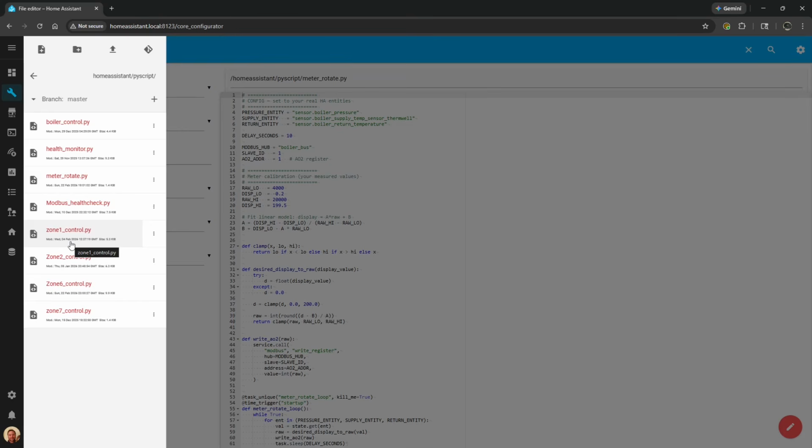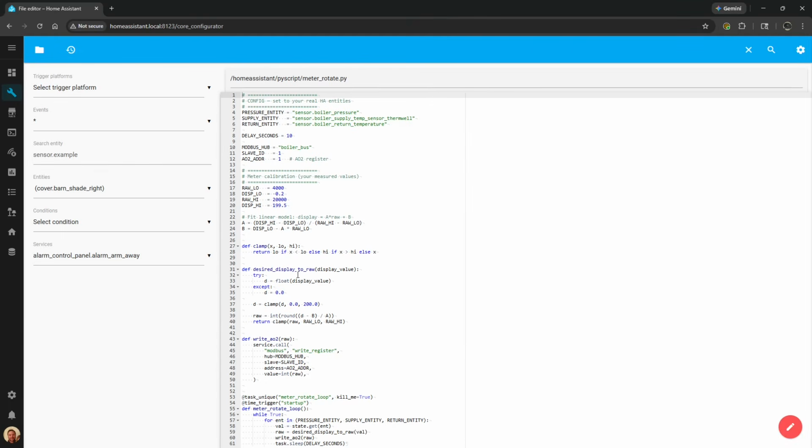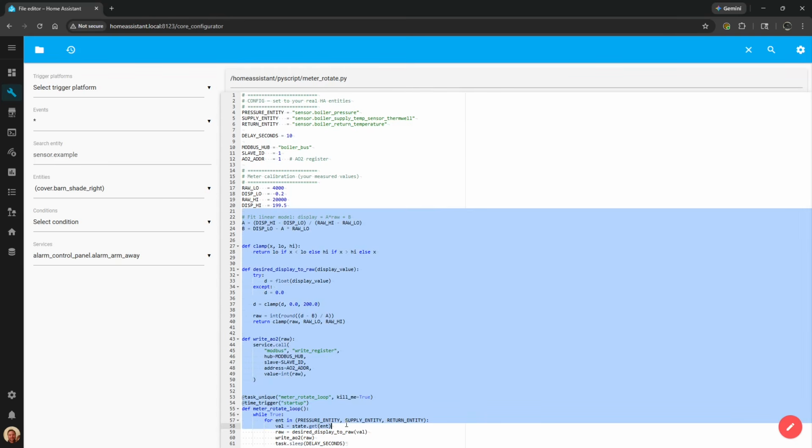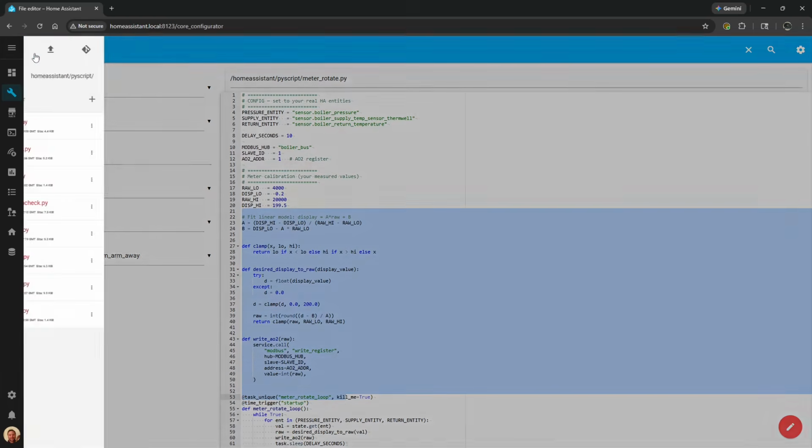So what I've done now is I've written a bunch of logic that, depending on what the temperature is outside, wakes up and runs some hot water through the zone periodically. As it gets colder, it runs it more often and for a longer period of time. It's basically a way to make sure that this zone never gets frozen.